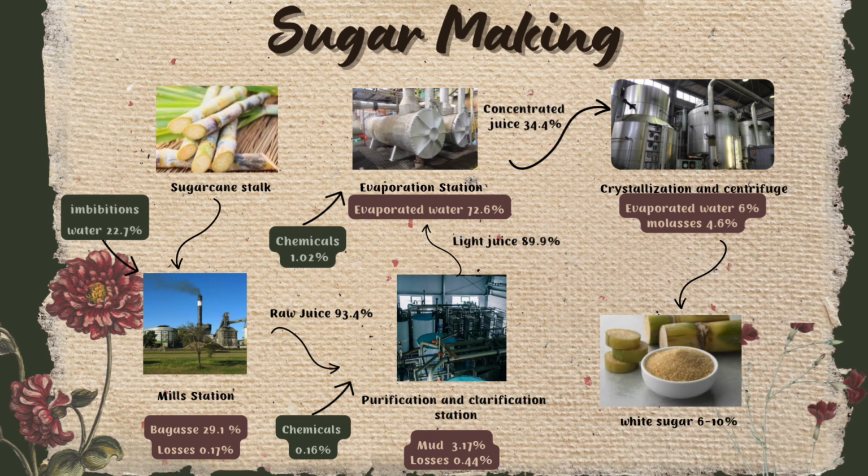At the mill station, the cane is mechanically unloaded, placed in a large pile and cleaned prior to milling. Then cane is extracted step by step in successive mills with adding imbibition water for complete extraction. The crushed cane exiting the last mill is called bagasse, which will be further used as the main component for pulp production. The raw juice from the mills is strained to remove large particles.